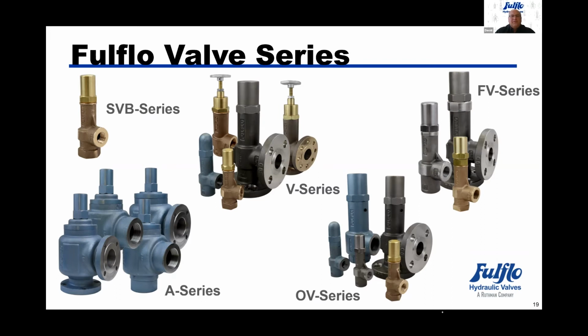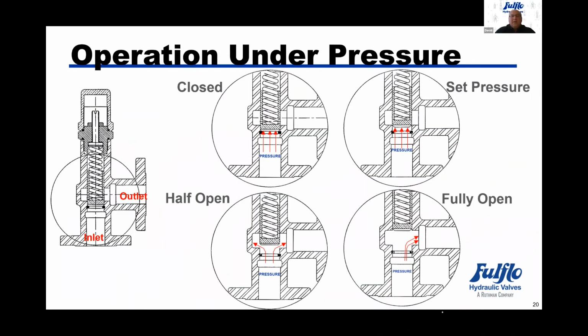So to understand how the valve operates, the valve is normally in the closed position. If you follow the red arrows up on the closed drawing, the piston, being closed, is down and sitting on top of the stop ring, which is a ring of expanded metal inside the relief valve body that would prevent the piston from being forced out of the valve.